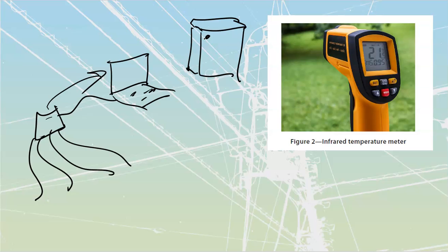So you're going to shoot the back wall, take a note of that measurement. Then you're going to go and shoot each of the individual components that you want to test, and your components should be roughly the same as the enclosure. If they're way hotter than the enclosure, you know that they're the source of heat inside there, and if that heat is on lugs and conductors, once again it helps you to track down that you've got harmonics on it.